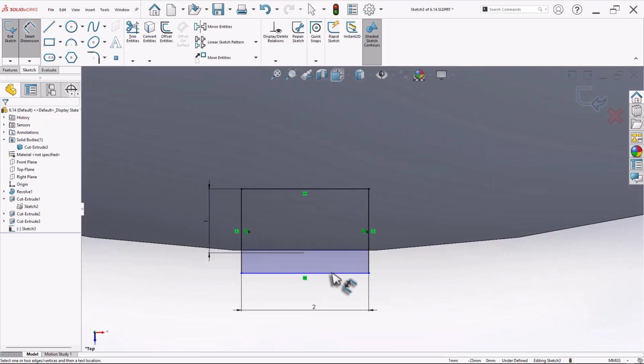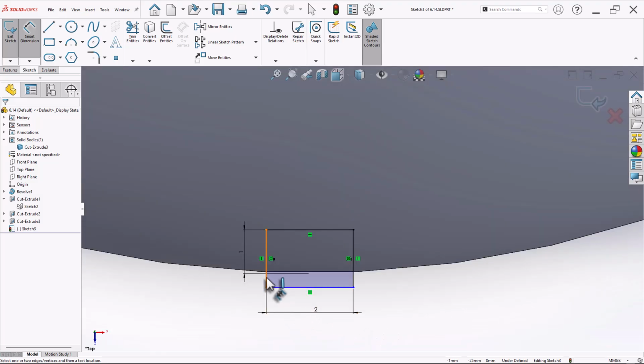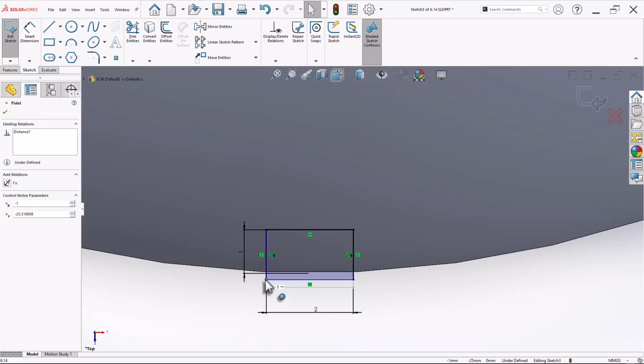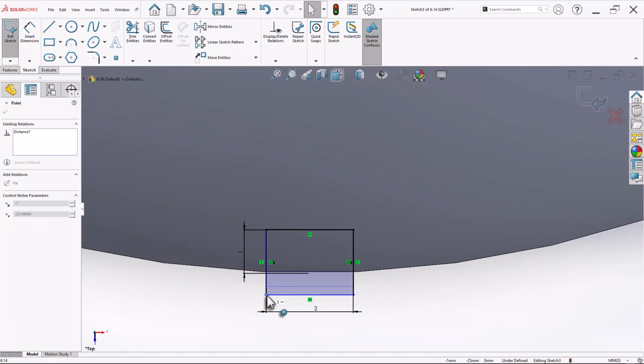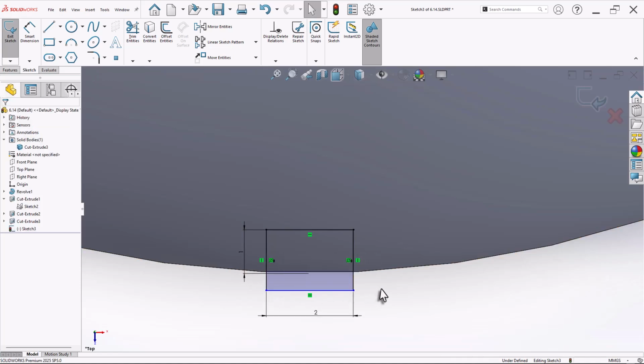So here press shift, select this and keep it 1. So we need to keep some part of a geometry outside of this circular line. Now why I am keeping this much of geometry outside? If I simply drag it and try to match with this, it is going to create very thin cut which result in two solid body. That's why deliberately I kept additional segment of a geometry outside of body.